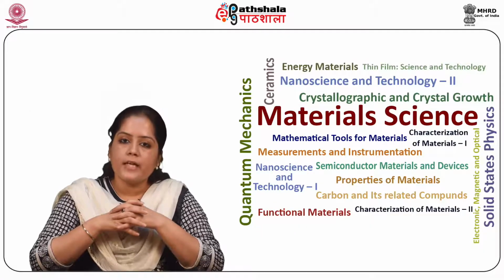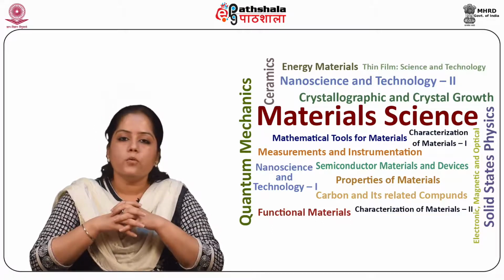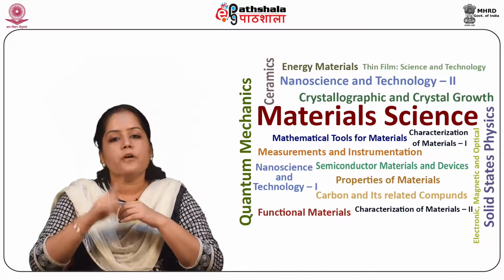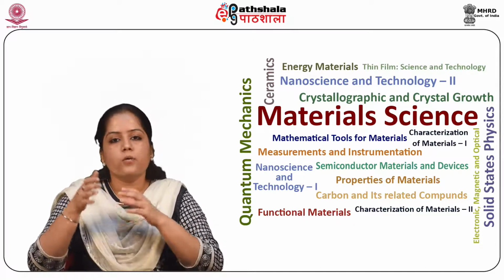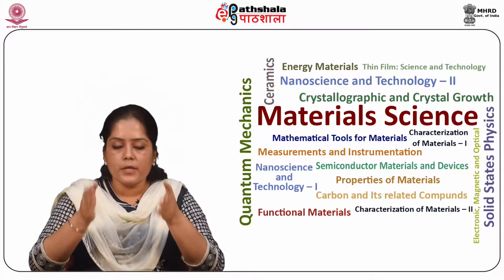Crack tip shielding by transformation toughening. The two important mechanisms of crack tip shielding in ceramics are, first, transformation toughening, and second, stress-induced micro-cracking. Many ceramics can undergo transformation toughening.